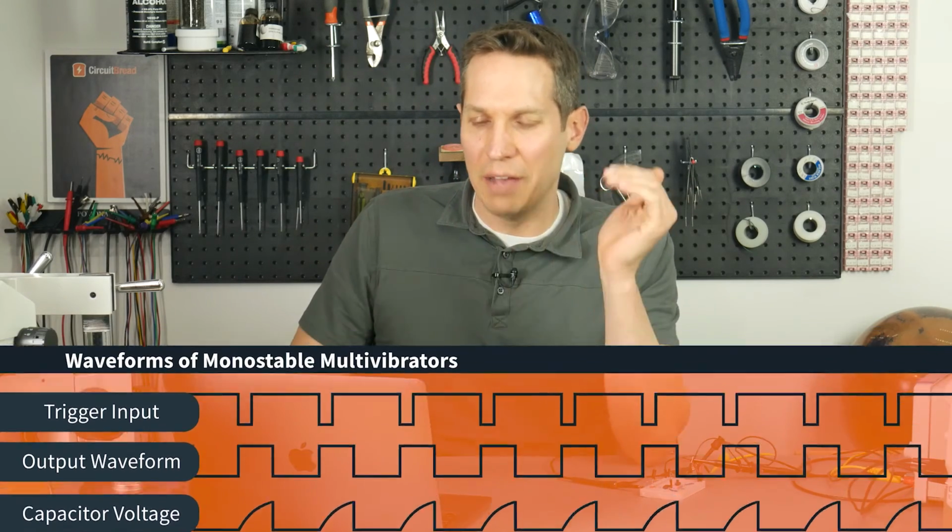And again, everything getting inverted and changing here, and the flip-flop changing states sometimes and not changing states other times, can be quite complicated. But once you walk through this a couple of times, it should start to make sense. And hopefully having the truth tables of the flip-flop visible during the different states will help out a little bit. Okay, with that, let's actually get the oscilloscope set up and show this in action.